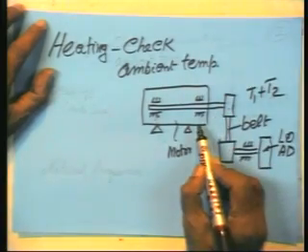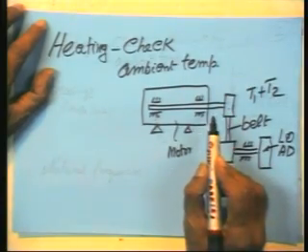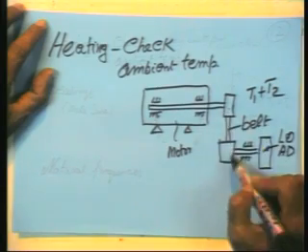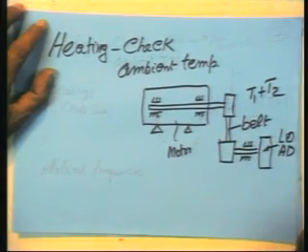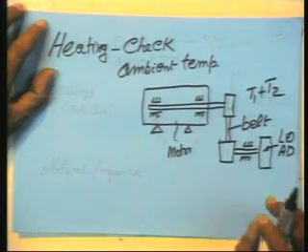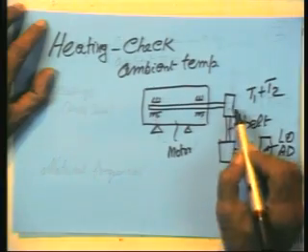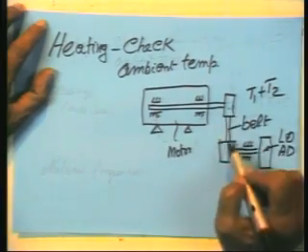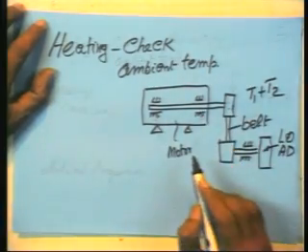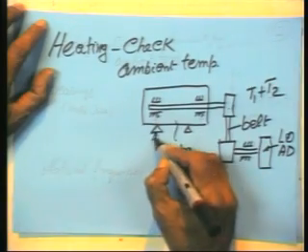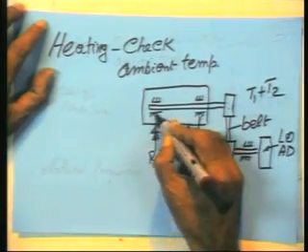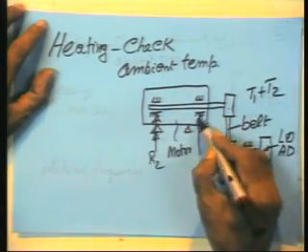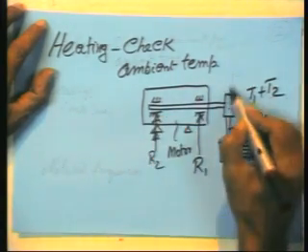Now you have purchased the motor, so you have to make sure that these bearings can take this up. That is something which you have to make sure. Many a time you may have to ask the manufacturer that you have such a particular load on it, the tension of the belt, can the bearings take it up? You can easily estimate the reaction on the bearings. This is one bearing, this is the second bearing, there might be R1 and R2, and there is a load here.